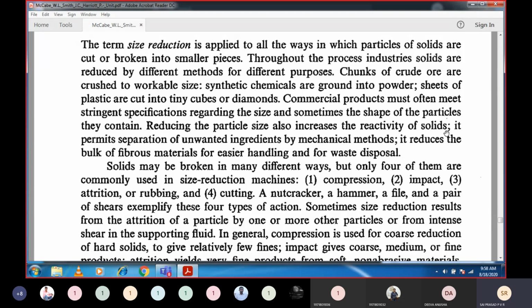For example, you take sodium and methanol. Sodium is a metal and methanol is a liquid. You add sodium into the methanol, what will happen? Sodium will dissolve first, and then in the liquid phase of the methanol, the reaction takes place. Now remember, if you put in lumps of sodium, these lumps will take some amount of time for dissolution to take place. Only once we ensure that the entire sodium is dissolved into the methanol can we ensure a reaction is triggering. So how do you reduce the time taken for dissolution? Reduce the size of the solid particles.